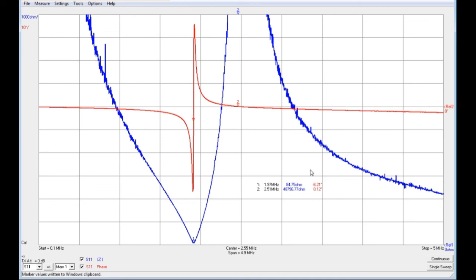Okay, so that really gives an introduction to how to use the VNA software to do these kinds of measurements on Tesla coils. If I had another pair of coils connected by the single wire medium, then we would start to get some of the types of data that are shown in other posts that I take. But this is an introduction to using the software to measure Tesla coil and TMT systems. And in subsequent posts, I'm going to be looking at coming back to also comparing with the HP 4195A professional vector network analyzer, and also having a look at transmission and through measurements, so S21 and ultimately Z21. Okay, great, very good.